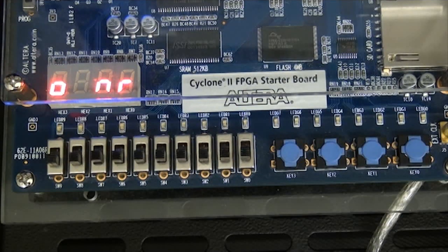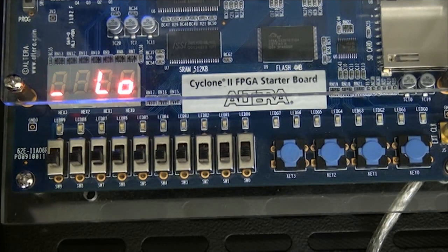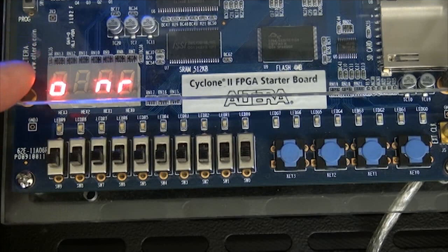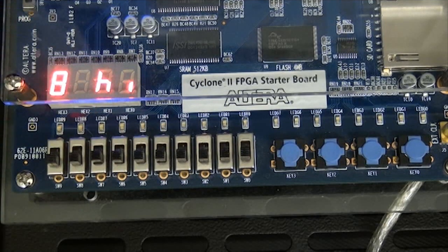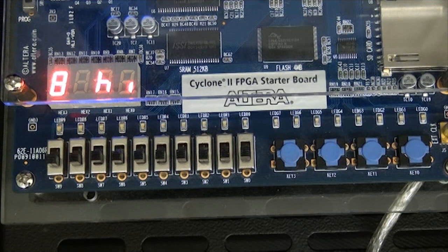So this is the very first thing that you should actually get working: these different symbols like the underbar, just a small 0, and the full 8 showing for the various levels of your peak. So for 0 to 0.2 volts, you should see just the underbar, you should see the 0 here and the NR for normal, and when it goes back to high, you should see the full 8 with HI beside it. If that's working, that's one of the parts of your project that you've got working, then you can continue on with the other parts.